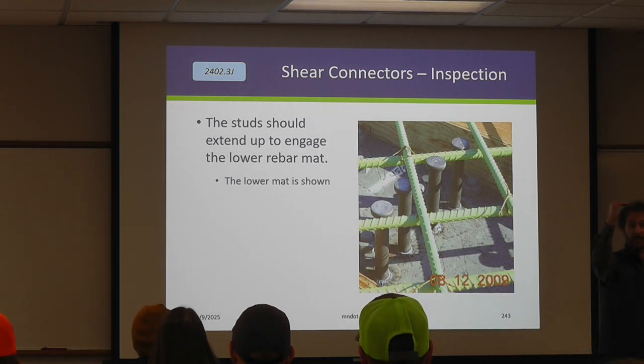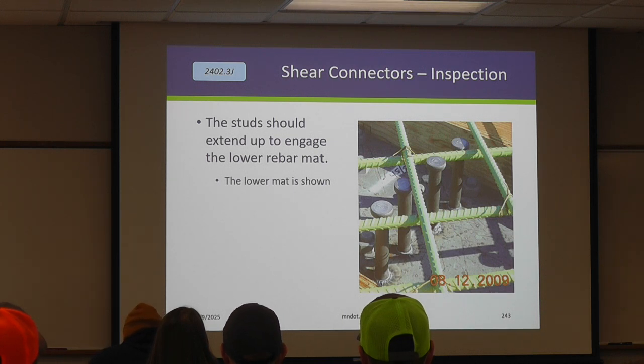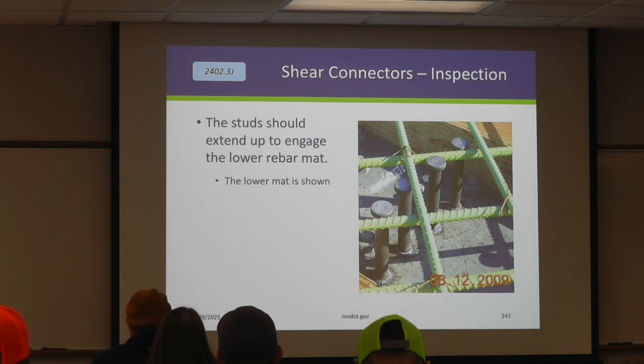The other piece is they have to be below the top mat of steel, because at some point in the future, we might come mill off 2 inches of concrete and we don't want to clip all the heads of the studs. So they have to be below the top mat of steel as well. And that's where you can potentially get yourself into problems.